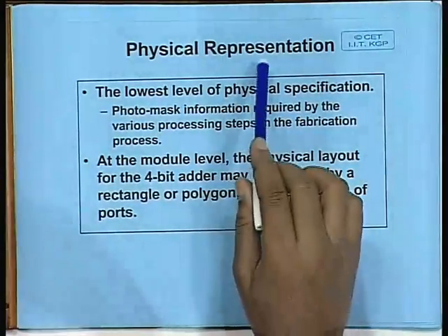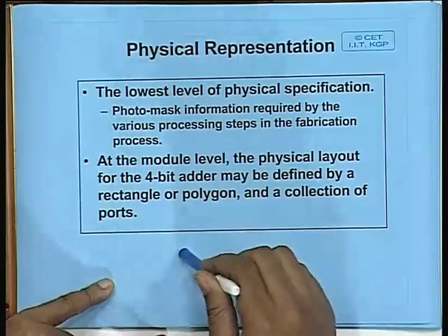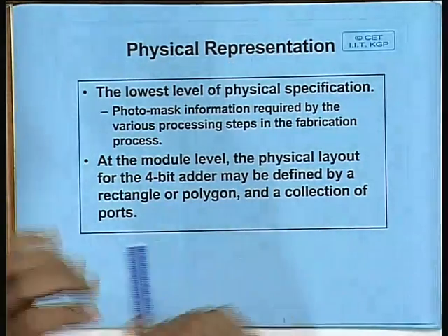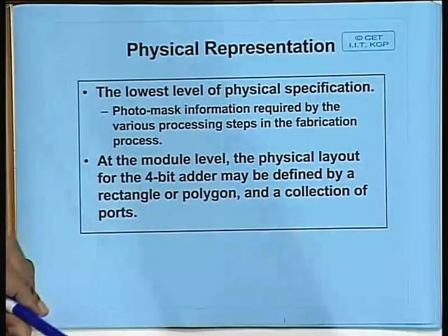So the third step that I was talking about was the physical representation in the Y diagram. So we talked about behavior, we talked about structure, we talked about physical. Well, just before I proceed further, let me tell you one thing: if your objective is to design a chip, then it is always instructive and always better to specify at the structure level as far as possible, because you may be tempted to specify in the form of behavior, since all of you are so familiar with writing a program in a high level language. So if I give you a complex design to implement, you may be tempted to write it like you write a program in C.